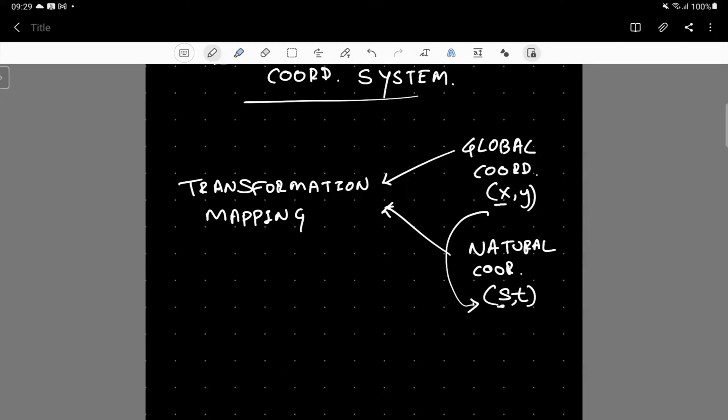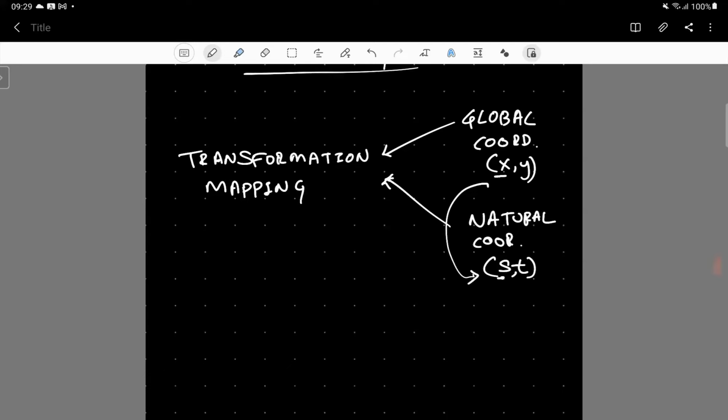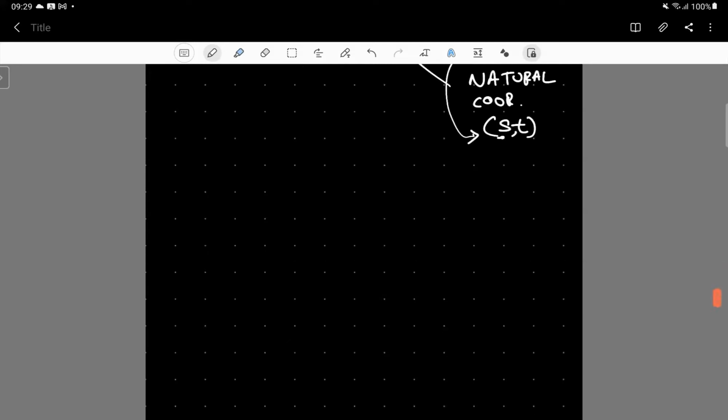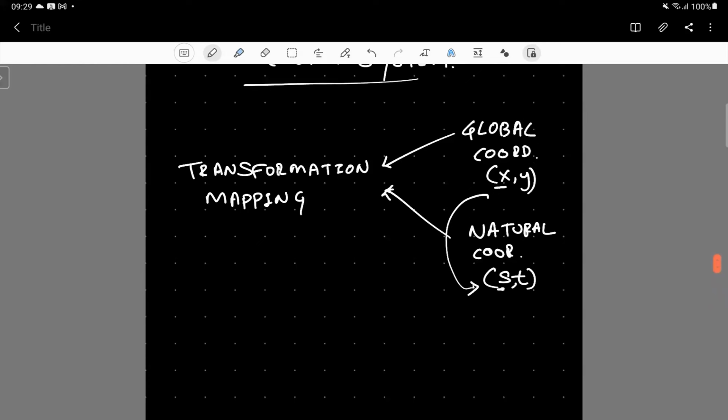Similar to that, of course, we are still in the spatial domain, but we do a kind of mapping from the global coordinate system to a natural coordinate system. So we do a mapping between the two coordinate systems. Let's try to develop the isoparametric formulation. Let's develop a stiffness matrix using the isoparametric formulation for a simple linear bar element. This is what our topic denotes, isn't it? Isoparametric formulation of the bar element stiffness matrix.